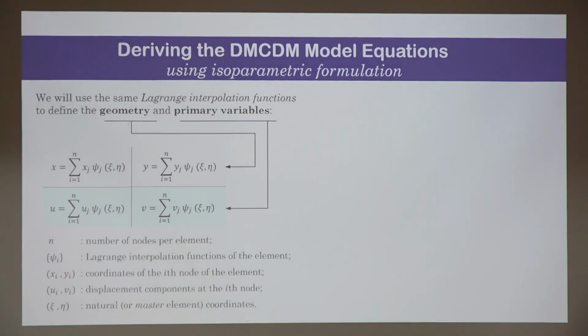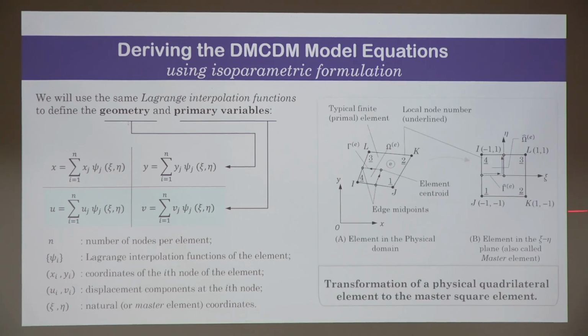Okay, and see the beauty of this: by bringing interpolation, all of it is taken over by numerical integration. Okay, so these are the transformations. Everything is in finite elements. So if you look at the control volume, that is, control domain rather, the control domain is actually here because it's on 4 different elements. So when you look at a typical element, it will have contributions from that element to the different nodes.